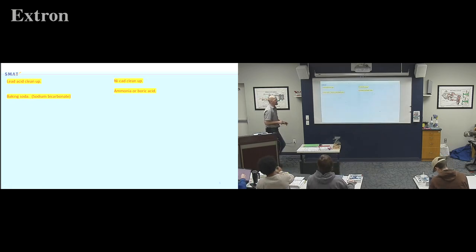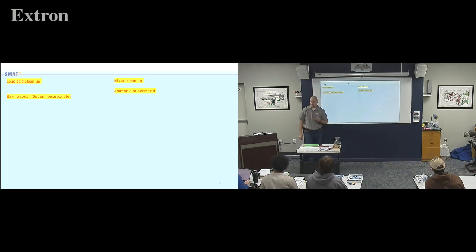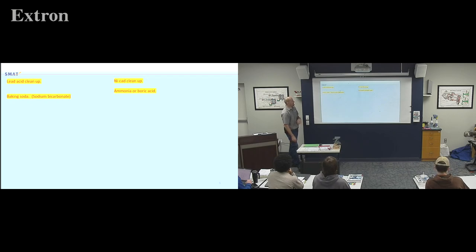Two different styles of batteries we use. Now, lithium ions are round. You're not going to see them much on small aircraft, and it's a pressurized container because the electrolyte is pressurized in lithium ion, so you're really not going to do much maintenance on them, and if you are, it's going to be really specific. So we basically don't cover much with lithium ion, other than it's a flammable or explosive battery that you've got to be careful with. As far as maintaining goes, we deal with lead acid and we deal with NiCad or nickel cadmium.